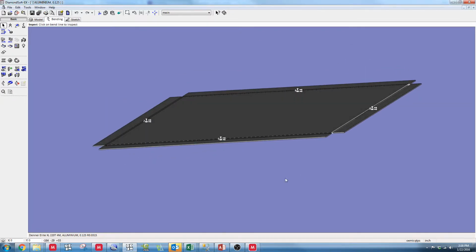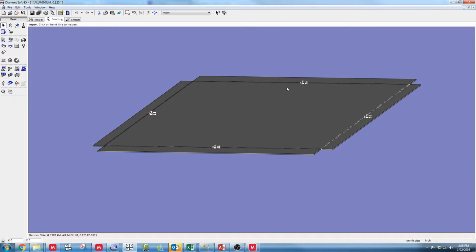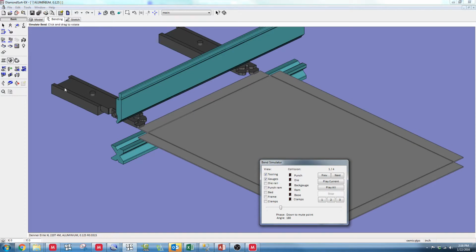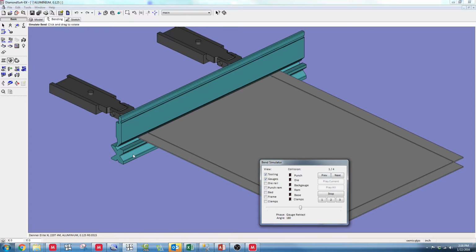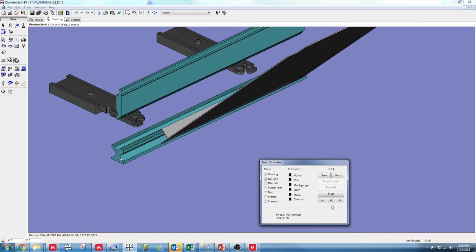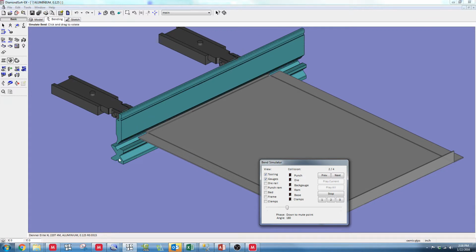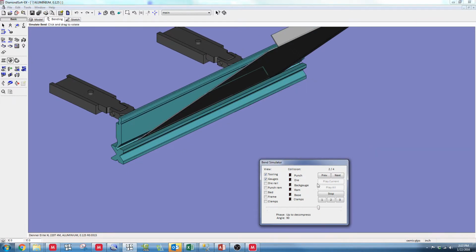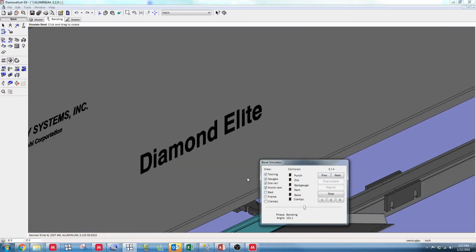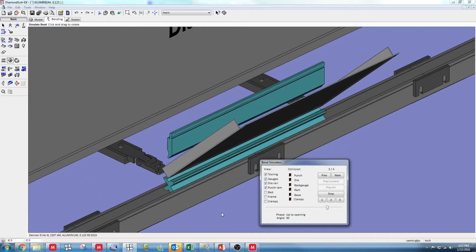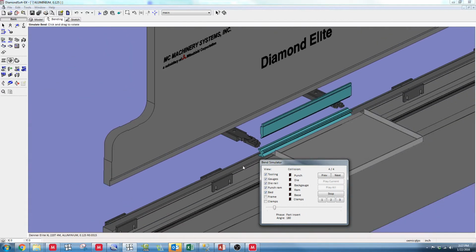And boom, you can see you've got a die and a punch associated at each of the bends. Then I come down here to this play button. It's called Simulate Bend. Hit it. And then we can just validate what this program is going to do. Bend 2. You can stop it, move it forward, move it back. You can see the different pieces of the puzzle here. So you can put as much stuff in the view as you want.